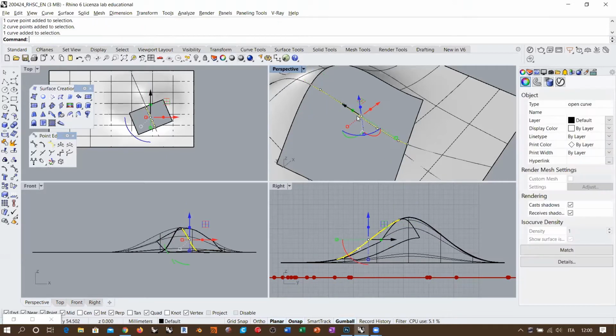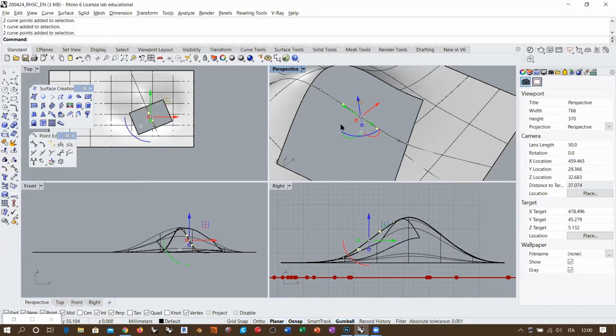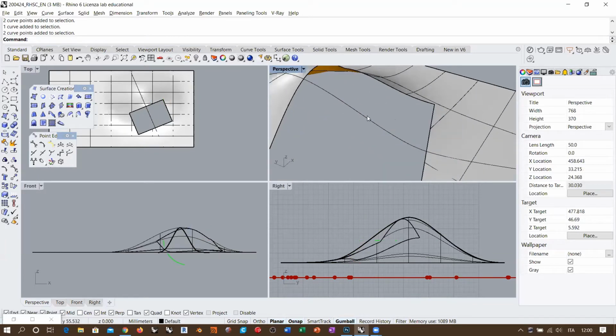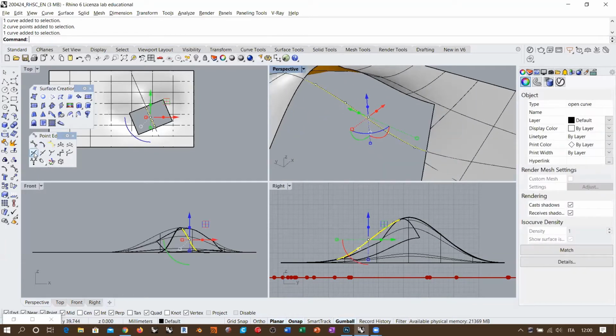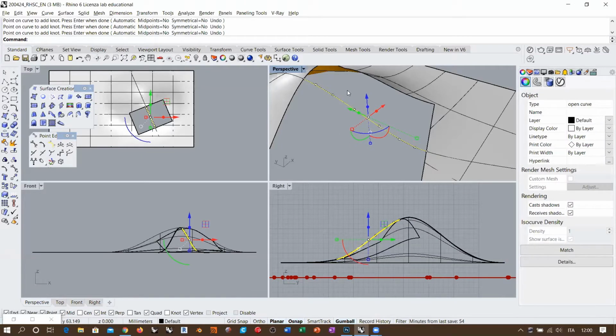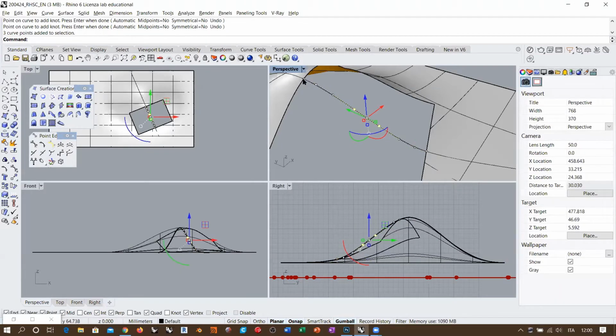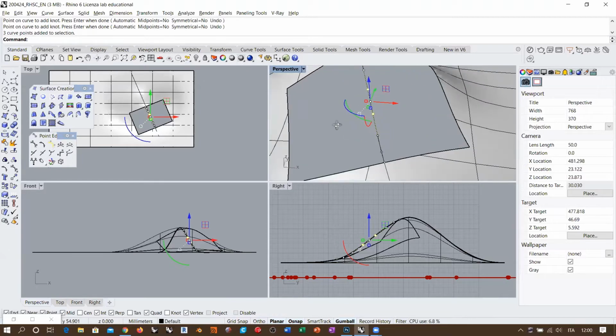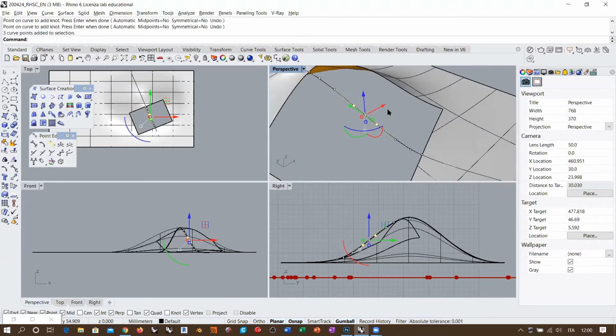Okay, so we just added these 2 control points that are useful for determining the curvature continuity along these edges. And if I want, I also can add other knots, for example, 1 here, 1 here, and 1 here, okay? Other 3 knots, which means other 3 control points. So you have 3 for initial curvature, 3 for final curvature, and 3 that this curve is a degree 3 curve. These points obey the rules that we saw for degree 3 curves in terms of topological editing.